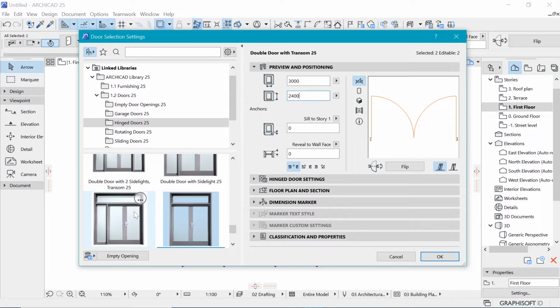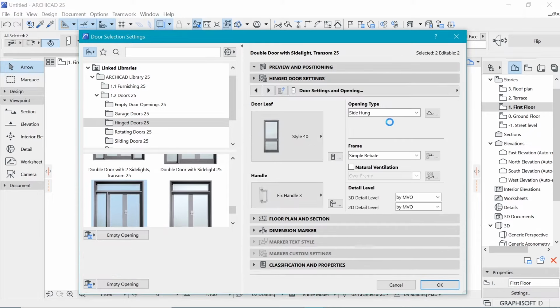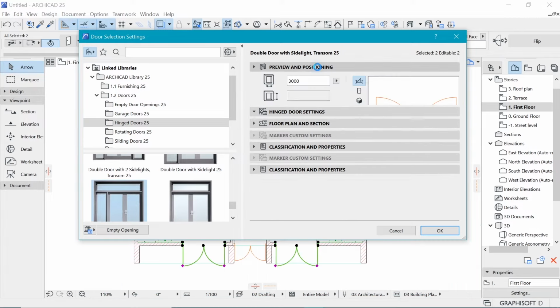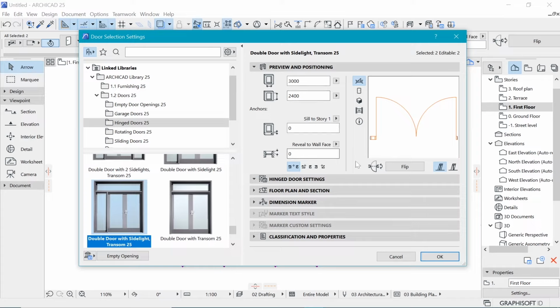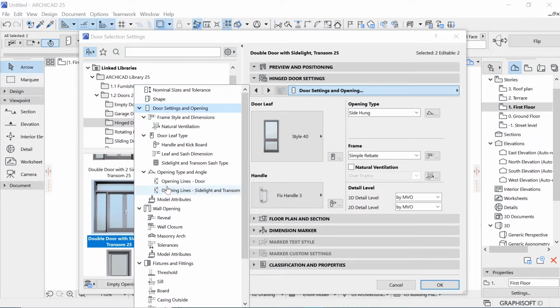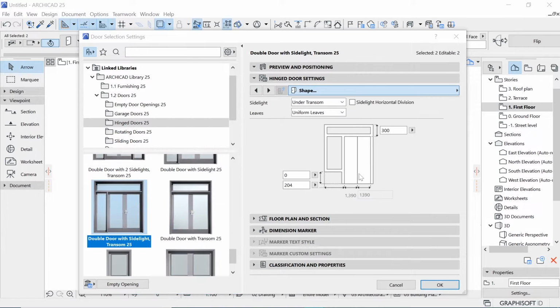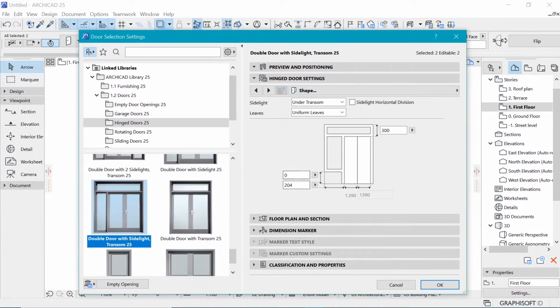So Control Alt, and then I click. When you Control Alt left click, it enables us to have the same parameters that are not changed, instead of going all over to change these things. Once we Control Alt click, we have just what we need, with everything set already. So now let's head over to this side shape where we can actually make this a little bigger, because it's a side light and it needs to be, I think, 1 meter or so.